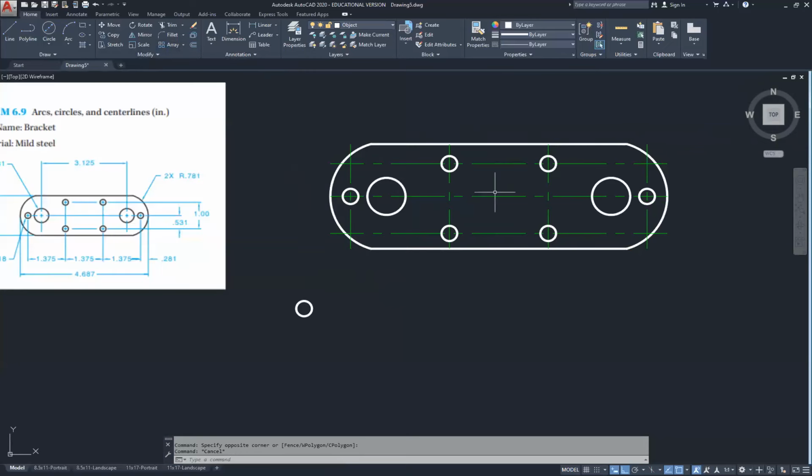And now that the drawing is laid out, I'm going to remove the excess information. These center lines we'll put back in with the centerline command. So we're going to remove them for now. Hit the delete key. All right. Now we're going to go ahead and change our layer back to center.